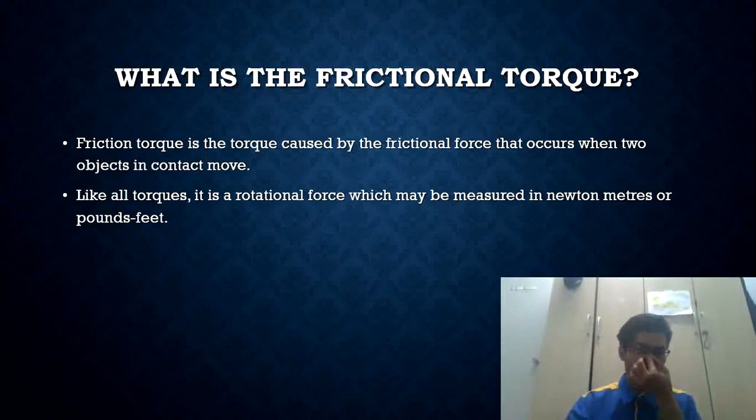Well, there is static friction when the motor is stopped. When the motor starts turning, you have dynamic friction. Most parameters of the motor are measured, and that includes the friction. All friction coefficients are measured. It is not a good way to say that A material with X surface roughness rubbing against B material with Y surface roughness will give a predictable coefficient. It has to be measured.